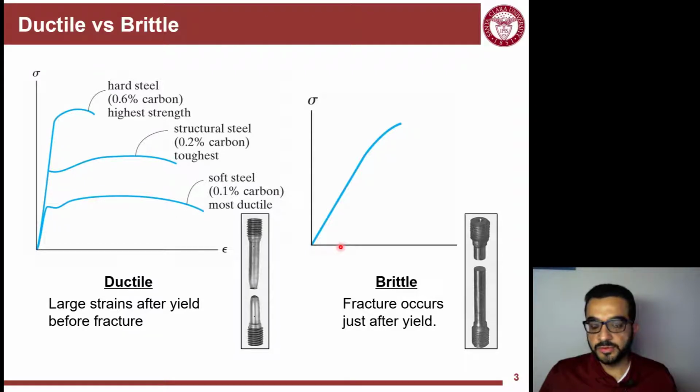They're used in different applications in life, but it's good to start categorizing ductile and brittle. With ductile, you have a lot of indication that the material will fail because you have that necking, so you can see it. But brittle is just sudden. In the lab, you'll have no indication at all. Boom! We'll hear a big bang, and the material fails.